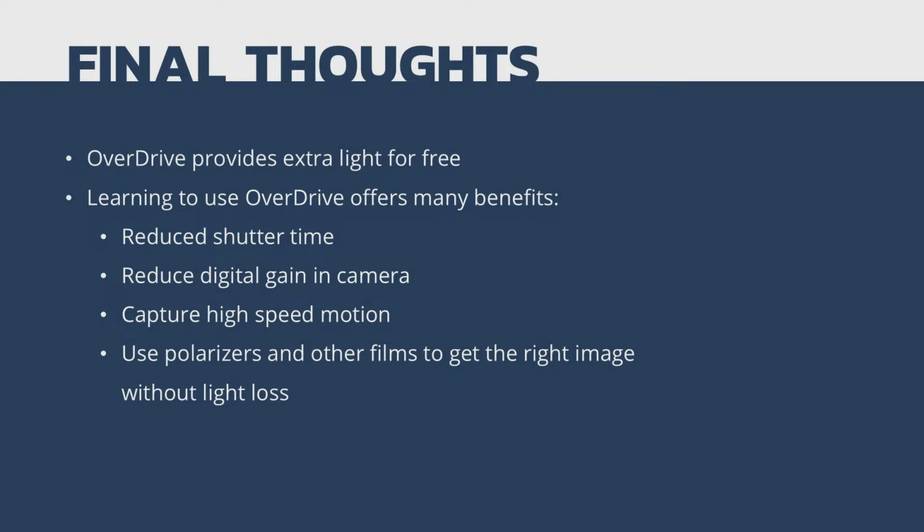If you don't take anything away from this presentation, I hope that you at least learned that overdrive mode provides you extra light for free from the same light, and that by learning to use overdrive modes and utilizing them, there are many benefits, including reducing your shutter time, reducing digital gain in the camera, capturing high-speed motion, using polarizers and other films necessary to get the right image without light loss. And there are just many benefits to having all this extra light.